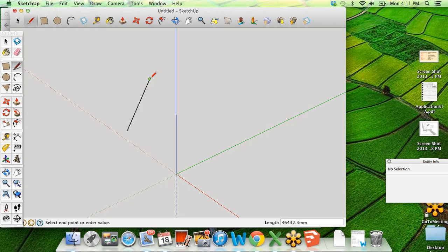Make a line. And what Sketchup does, which is really smart, is it will guess what we want to do. First, it just tries to align with that axis. But if I travel along this edge, and I get to the midpoint, and then I travel over here, do you see that red dotted line that created? I kind of got Sketchup to infer that I wanted it to let me use that midpoint as an inference point. So let's say I wanted to create another line that went from the midpoint outwards.